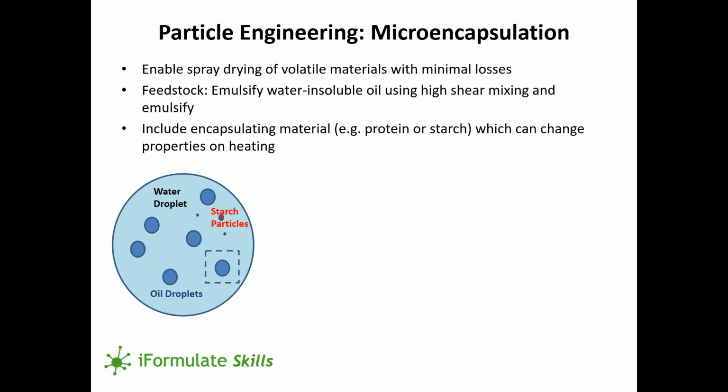Let's talk here about microencapsulation and more complex structures that can be formed within the spray-dried particle. So maybe you want to encapsulate a volatile oil, a fragrance or a flavor, for instance, within a solid particle. Here your fluid feedstock will be an emulsion of that oil in water, for instance, and included in that feed will be other materials such as starch or a protein, as well as a filler polymer on top of that as well. So that's on the left-hand side here.